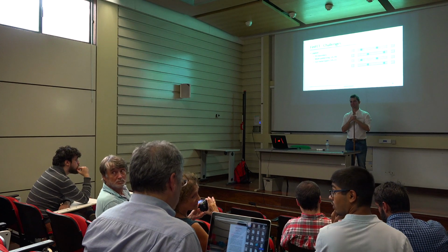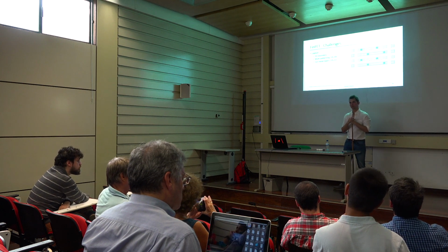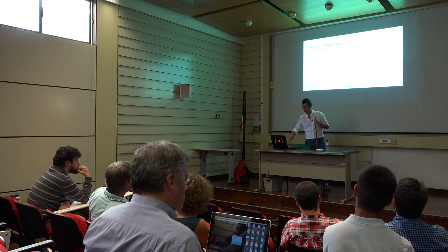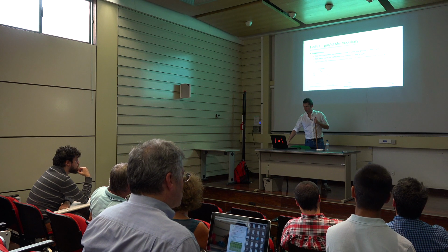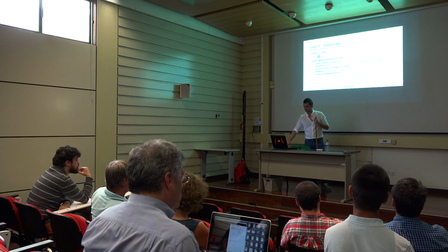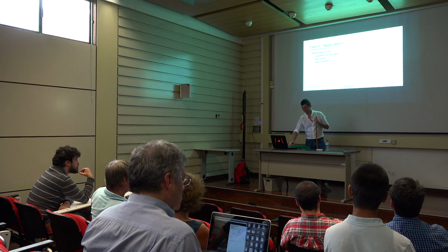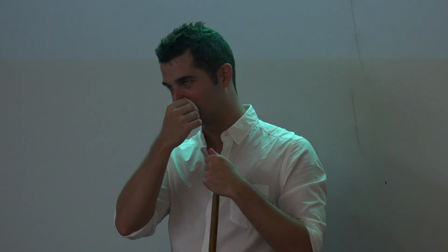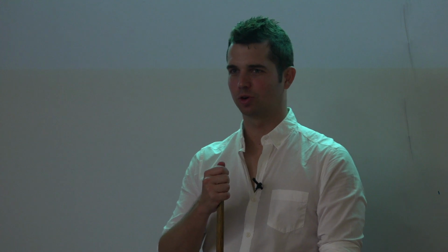In the advantages, you say that the intrinsic gain is higher. Yeah, the higher gm over ID. So this means that analog designers are coming back, working on this technology, or is it still digital designs? That's a tricky question, because analog designers care mostly about gain, and gain comes from the length. So yes, there's room for analog design. It's harder to achieve due to the size limitations.